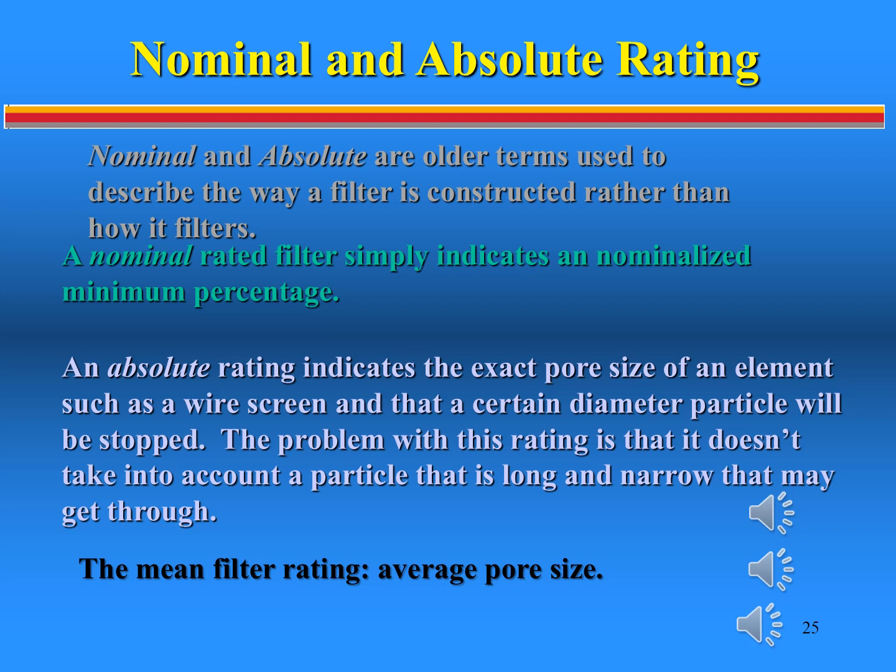Pore size is modified by the form of the filter element, and it is not necessarily consistent with the actual opening areas. Furthermore, the actual form of the contaminants is not spherical, and the two linear dimensions of the particle can be very much smaller than its nominal one, permitting it to pass through a very much smaller hole, such as a cylindrical particle with a thickness less than the slot opening of the filter.